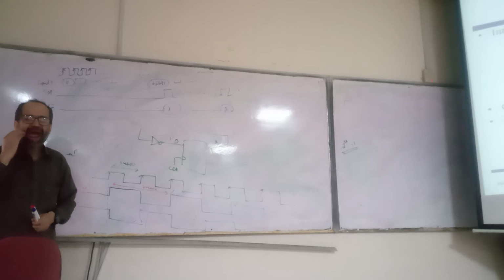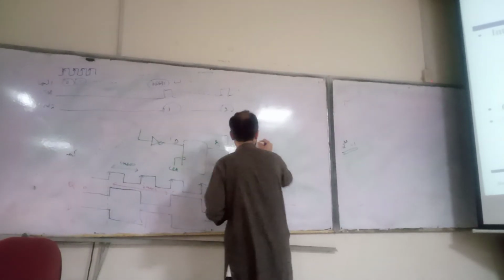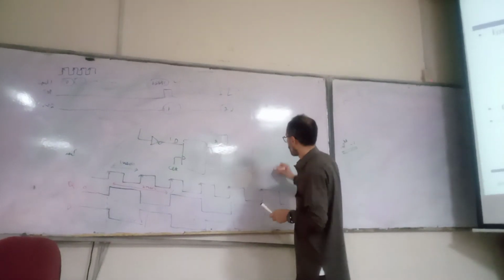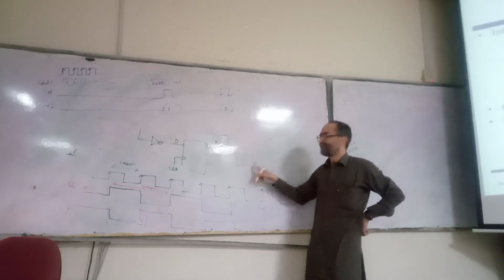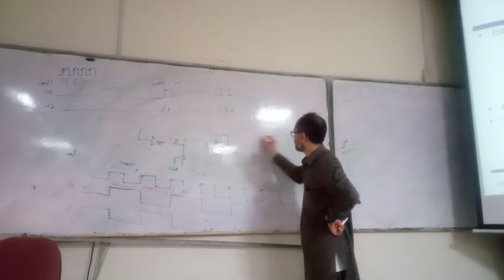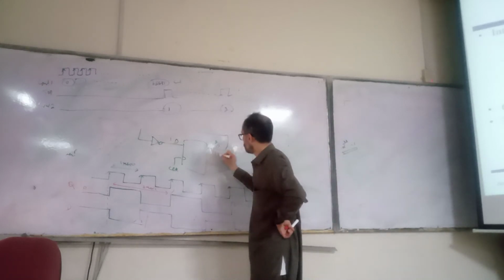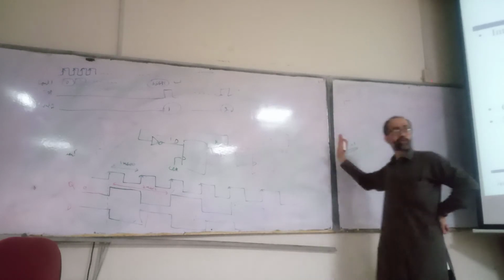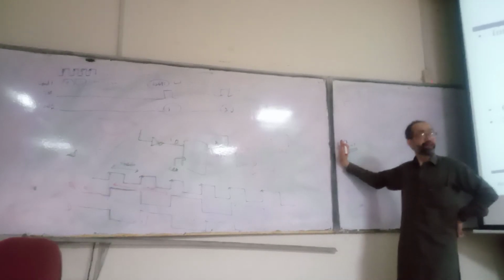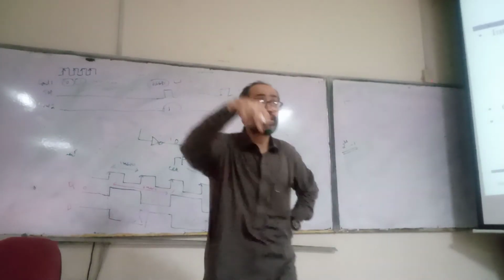Use another flip-flop, cascaded. We can use another flip-flop, and this Q can then be the input here. So this is clock by 2, then it is clock by 4, and then again with another flip-flop, clock by 8. So actually dividing a clock by 2 is easy to implement.